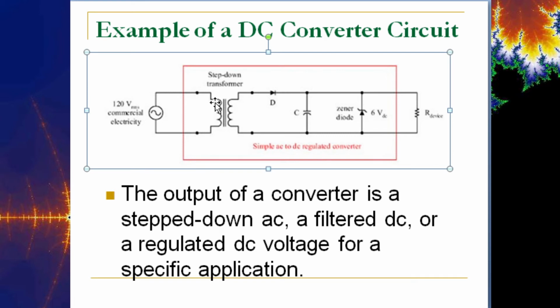So you might be saying, well, what happens on the negative half of the cycle? Well, the current is going to try to be pulling in the other direction, and this diode is going to be in reverse bias at that point, and it will block it. This is what we call a half-wave rectified signal, because you send an AC signal through a single diode, it's only going to pass through the positive humps, and then it's going to be 0 for the negative, and then it'll go positive again. So this circuit is only going to get positive voltage, and the current is only going to flow in one direction.